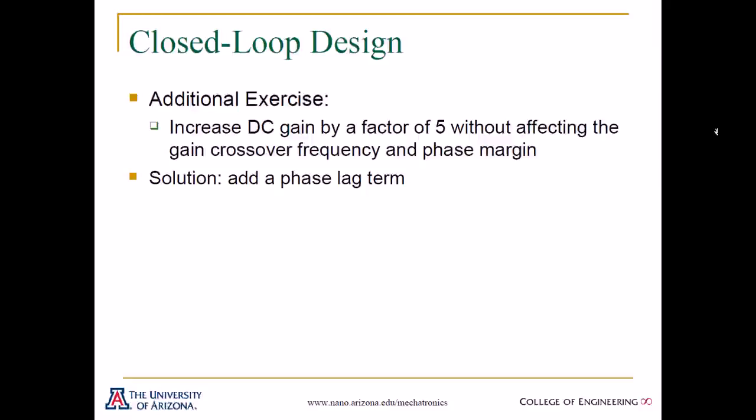To demonstrate the ability of RTW to implement higher order controllers easier and faster, we have developed an additional exercise where we require the students to increase the DC gain of the system by a factor of 5 without affecting the speed, that is the gain crossover frequency and phase margin. This can be accomplished by adding a phase lag term in series with the already designed phase lead compensator. I have asked my student Joshua again to complete this exercise using the SISO tool.